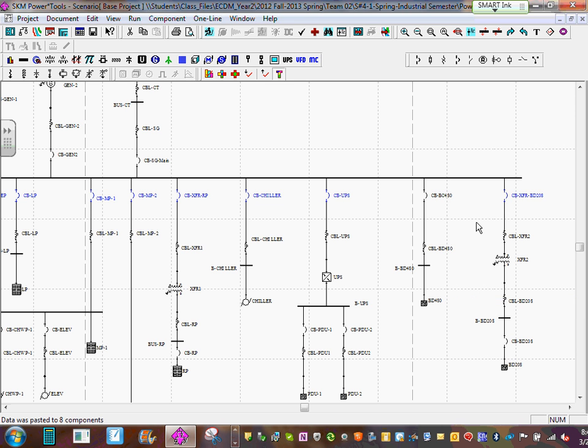Paste data. Now, what you did, Karen, is you put the same type of circuit breaker in each and every one of these circuit breakers. Now, Adam, you need to go adjust them. I'm going to do one with you guys, and you're going to do the rest. So I'm going to go to Derek. What's the transformer, the 208 bus circuit breaker? Did you size that one?